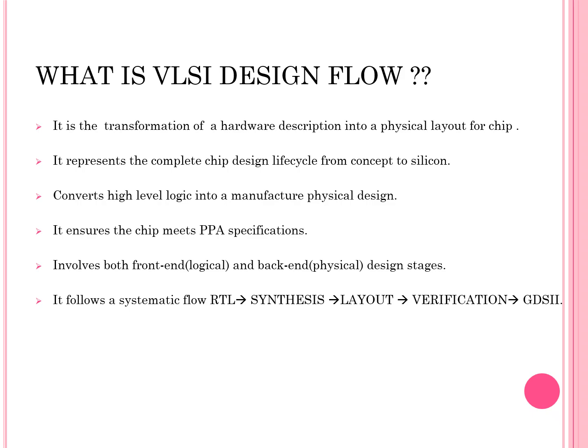This process involves both front-end design, which focuses on the logic and coding, and back-end design, which deals with the physical implementation. Overall, the design process follows a systematic sequence, which is RTL to synthesis, then layout, then verification, and GDS. So basically, VLSI design flow is the journey that takes a digital concept and turns it into the real working integrated circuit.